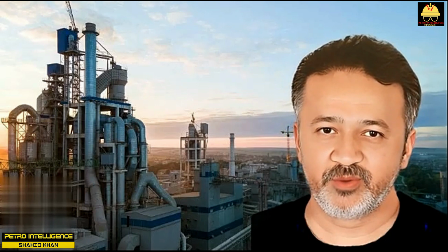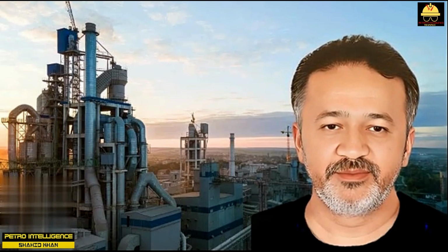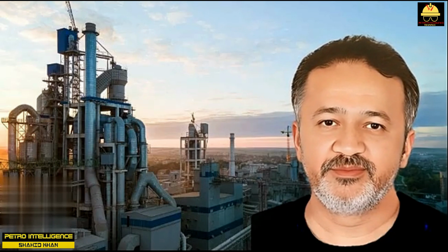Meanwhile, the flow of crude oil through those tubes that started out running faster increases. The crude oil flow is backed out of the slower tubes by the fouling deposits. The extra flow increases the velocity in the tubes that initially ran faster. The higher velocities retard the buildup of fouling deposits. Also, the greater flow keeps these tubes cooler. This also discourages the accumulation of deposits inside the tubes.